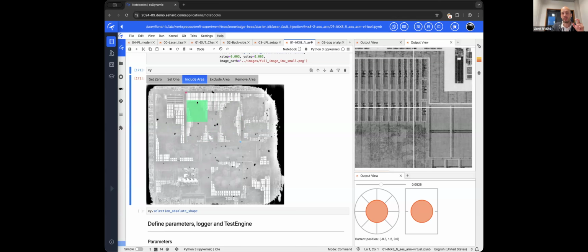Again, if I do that, I will target these white things, which are memory cells, and my goal is really to target the AES encryption itself. So I would, I would say, reduce a bit the area that I want to cover to only the logic that will be interesting to me. Okay, so I can select areas like this.